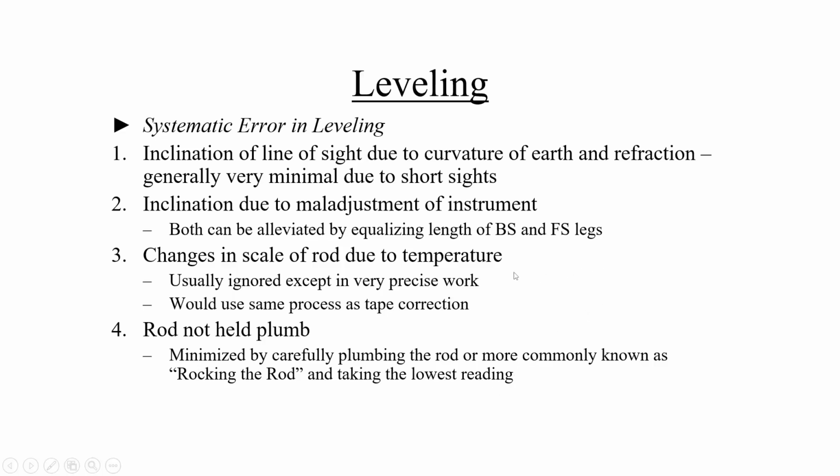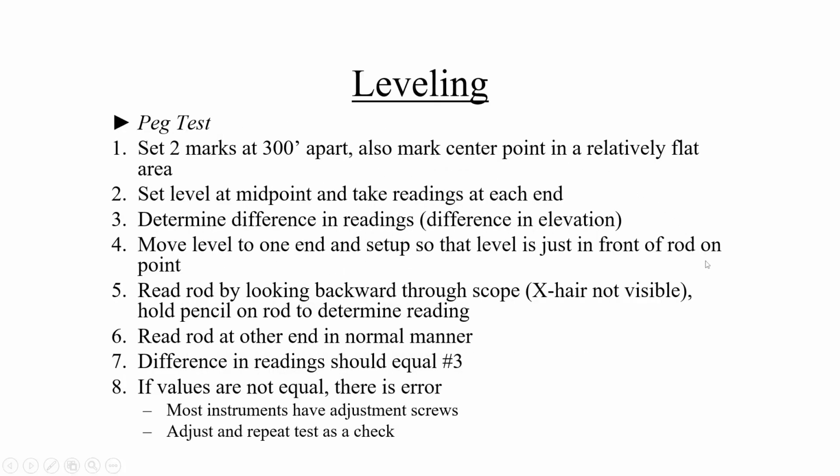We always have some different errors in leveling. First of all, systematic error: inclination of the line of sight due to curvature of the Earth and refraction. I will explain these errors later in our presentation. Here you can see the tests.